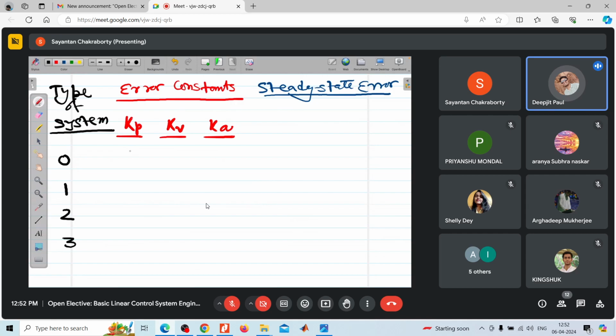So jerk constant? If we want a system where the jerk will be 0, okay, you can move on, but that is a very restricted application. Normally up to acceleration is enough, because I'll tell you, it's a very important thing. If you consider the jerk, then the system will become a third order system.